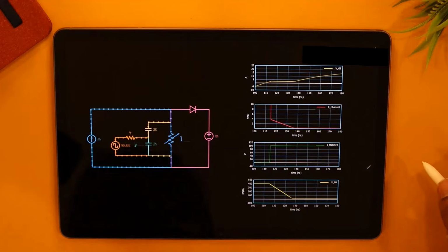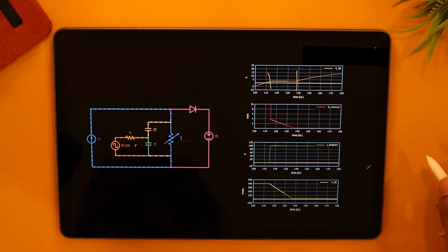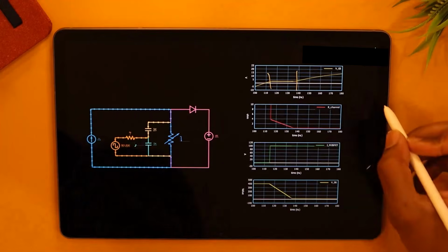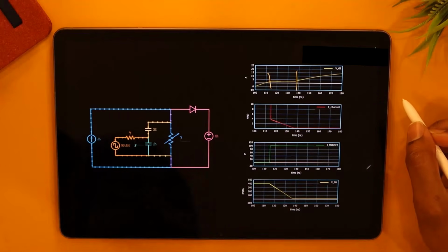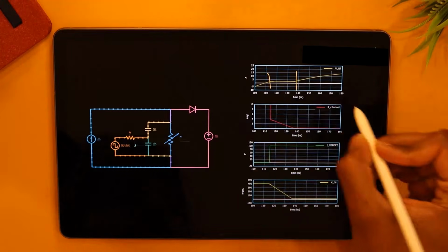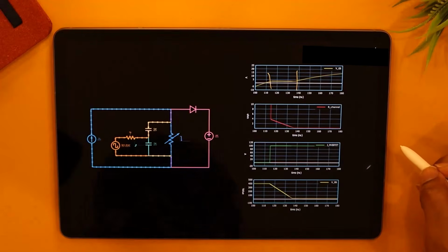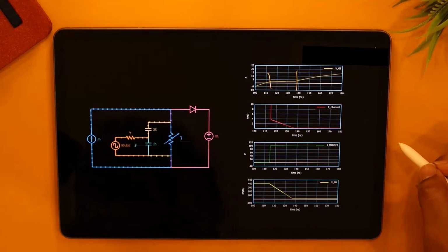Now let's try to understand how the plateau sustains, this region here. We know now that VGS cannot increase. If it increases, it will kill itself by creating a short circuit, right? It has to remain flat. But how is it sustaining for that long? And what decides the duration of the plateau? That's what we are going to understand in this second part of understanding the plateau, how it sustains.